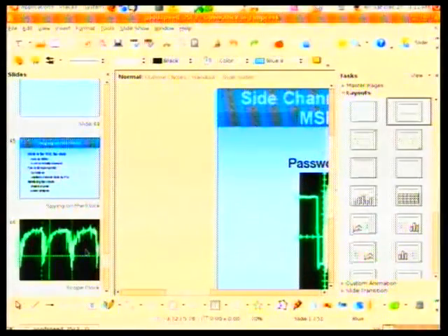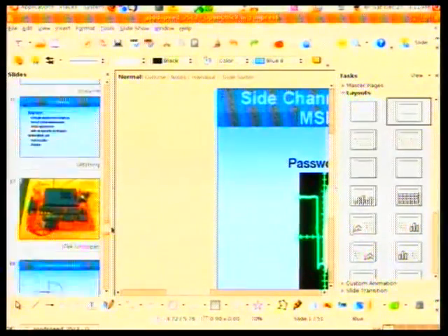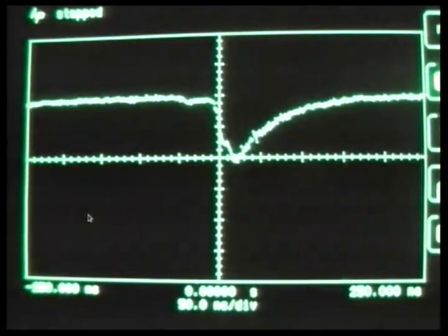How long did you say the timing glitch on the voltage rail had to be? I've had luck with about 45 nanoseconds. And you managed to generate that with the muxes and an msp430. What speed is the msp430 running at? I'm not sure how much of this is affected by the capacitance of my probe, but you'll see that it's not a very square drop.